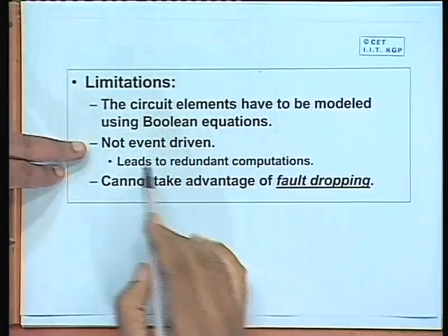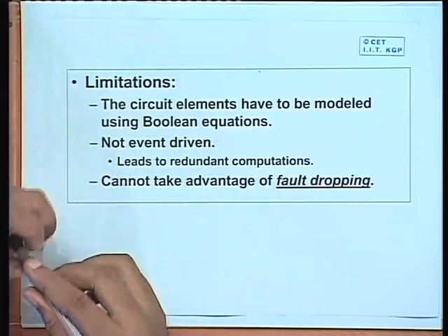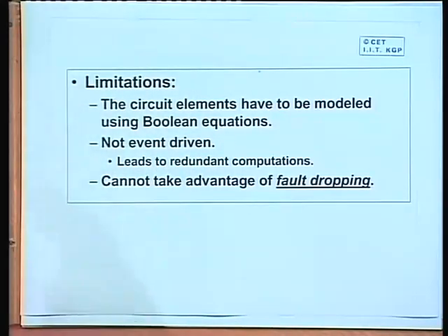And second thing is that it is not event driven. Event driven means sometimes in order to speed up the simulation process, suppose we apply one input to the circuit, we simulate to evaluate the output. Now we apply the next input. After applying the next input, we find that only in a small portion of the circuit there are some changes in the logic values.